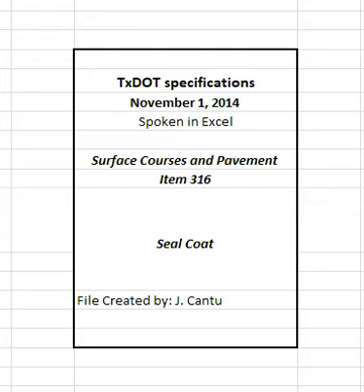2.1 Asphalt. Furnish asphalt materials meeting the requirements of Item 300, asphalts, oils, and emulsions. Furnish Type 2 or Type 3 AR binder in accordance with Section 300.2.9, asphalt rubber binders, as shown on the plans. Furnish a blend design for approval. Include in the design, at a minimum, the following.